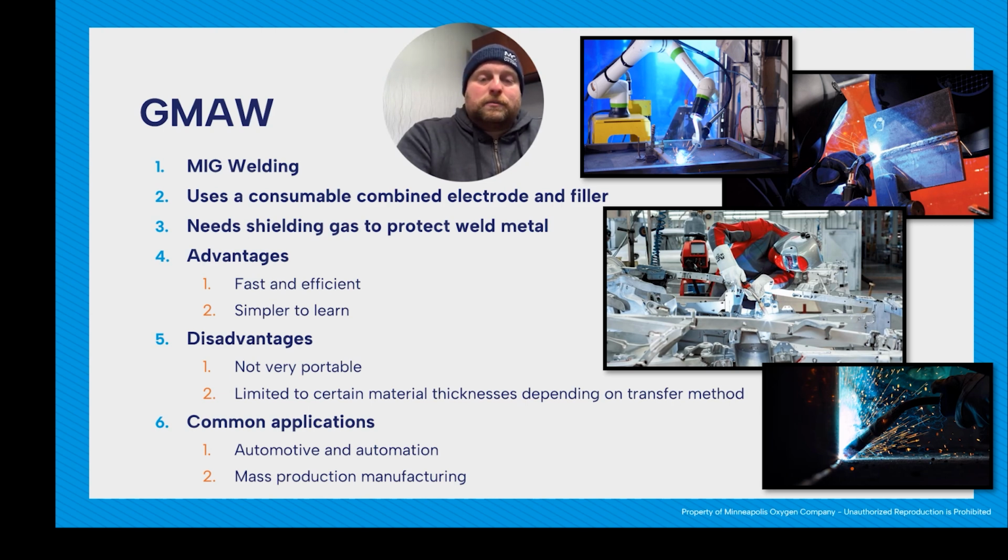With GMAW, if you watched the previous Welding Wednesday, you'll remember we talked about the history of welding and how wire feed or GMAW welding was invented about 30 years before they started using shielding gas. So it was used as a bare metal for quite a long time. Some advantages are it's fast and efficient. You're using all your material, really. There's very little waste. You can move really fast because you usually have a big spool of wire, so you don't have to keep switching out your electrodes like you have to do with stick.